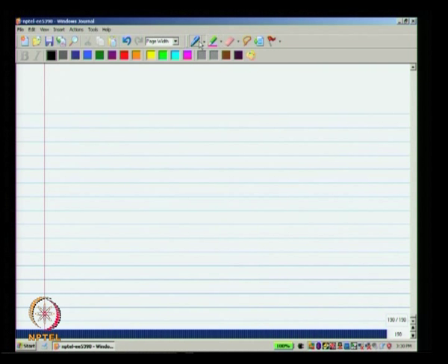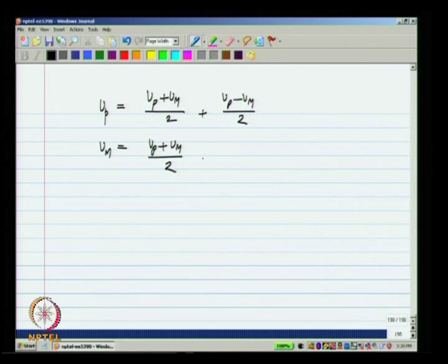Now, why were we thinking of common mode and differential inputs? I have explained this before. So, any signal, let us say if we have a pair of signals, instead of thinking of independent signals Vp and Vm, we can think of them as their average value plus half the difference and minus half the difference. Okay.